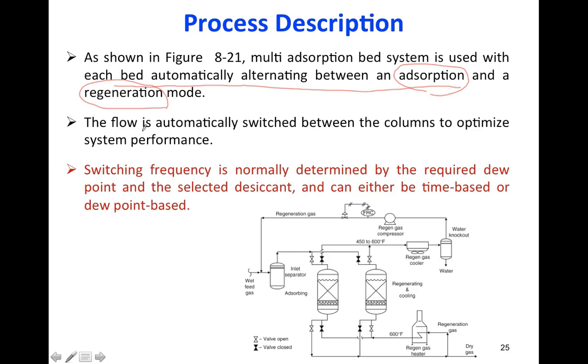The flows are automatically switched between the two columns for optimized performance, and the switching frequency really depends on the required dew point, how much water we want to remove, and the type of solid particles that we have.